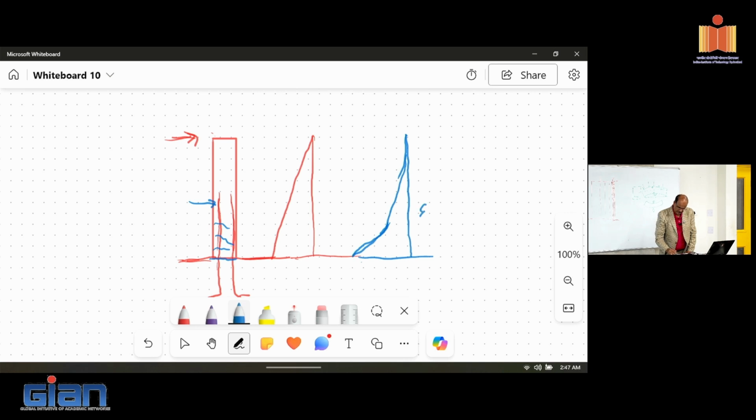So this is basically strain, if I call this bar ε1, right? In the uncracked section you will have a pretty small value, and then it will increase as you go down in the cracked section. So I'm saying it's yielding all the way to here, so let's call it εy, and then I have a value here, let's call it εx, at the foundation.